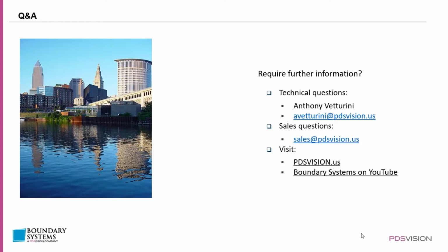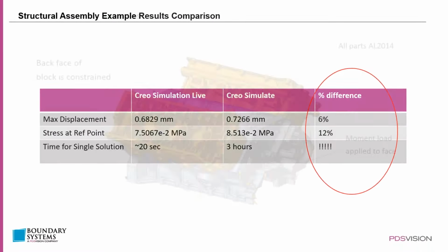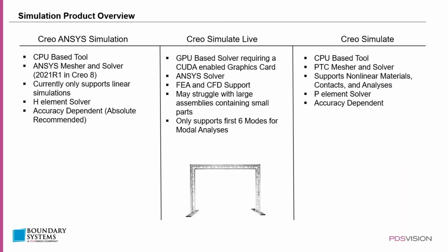One question I just got in now is, what are the hardware requirements for Simulation Live? If I come back to this slide, we see here it's a CUDA-enabled graphics card, which is an NVIDIA graphics card. There is a specific list of approved CUDA cards that PTC has that I'll send you. But overall, in general, if you have an NVIDIA CUDA-enabled graphics card, I'll show mine in a moment, Creo Simulation Live would work.